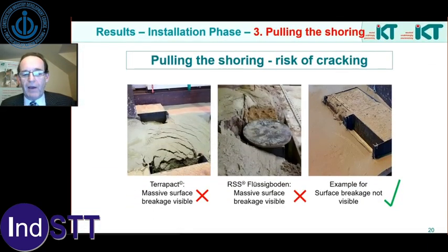When we pulled the shoring out, that was interesting. Now, we don't know when to pull it, so we asked the advice of the suppliers. How long do we leave it before we pull the shoring out? So it was more their decision, and we discovered we've got a range. We look to the right here. We've pulled it out, it's refilled, and we've got no cracking.